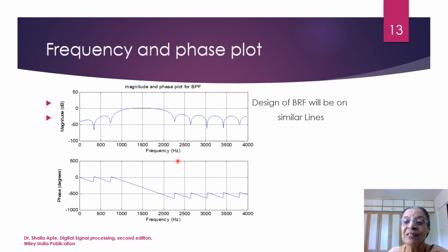In case of the frequency sampling method, what we do is we assume that there will be some small ripple in the pass band. We assume that there will be some stop band oscillations. That is what we call the Gibbs phenomena. And for these stop band attenuations, we try to select the particular points where we want to have the desired response. So we will select the frequency points as per the desired response.